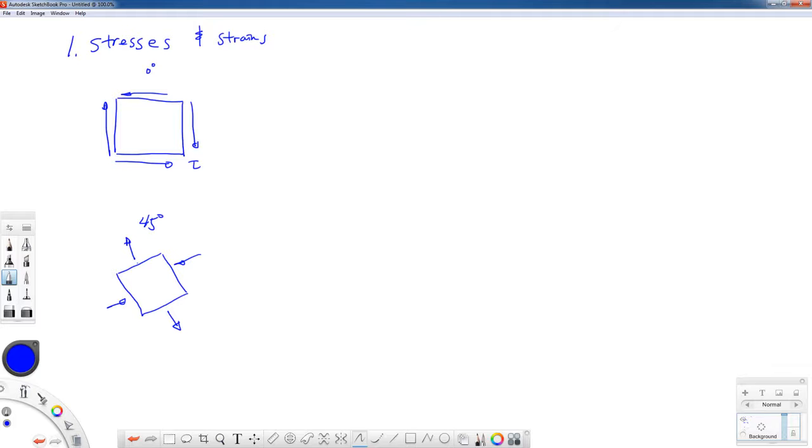Alright, so I just redrew those two blocks showing my shearing stress state and my normal stress state maxima. And the value of this in magnitude is tau, and the value of this magnitude is also tau. This is at plus 45 degrees and minus 45 degrees.